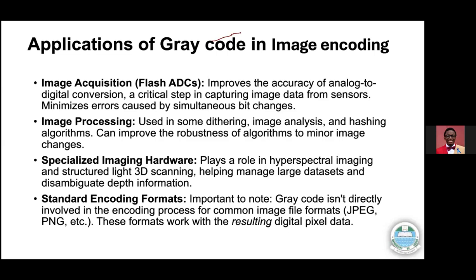Again, we're going back to the fact that only one bit is changing. If you're trying to ensure that the security of the system is proper, with no anomaly, no errors, no breaking, then once you see that more than one bit has changed, or something unusual has happened that you don't expect with gray code, you know that there's a problem there.